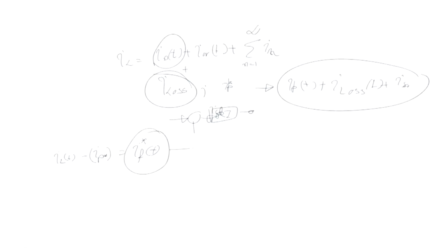Generally, it is compared in ABC with what actually you are injecting, and that you feed to the PI controller, then you have a PWM block and that has a switch, so for the one leg. Similarly, we have 3 such pulses. Generally it is unipolar in nature for the 2 level inverter, and accordingly for the multi level inverter we have a multi level switching scheme.